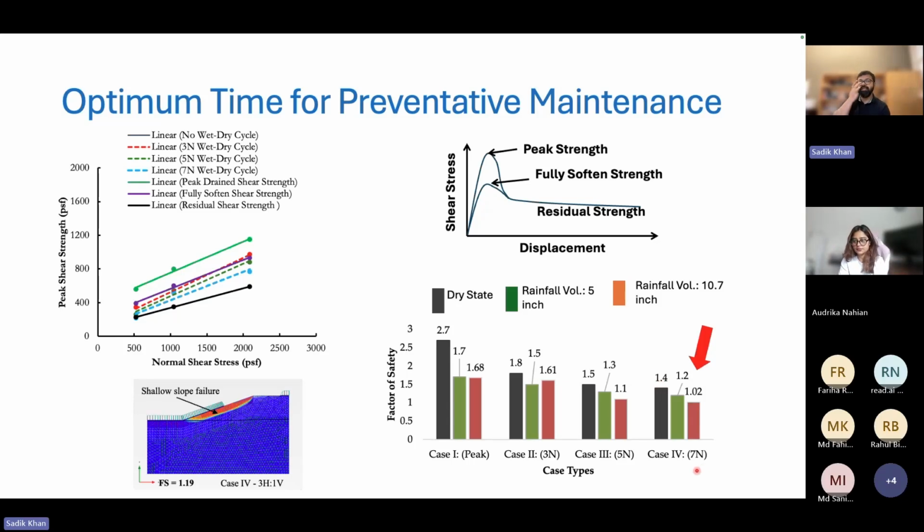particular soil. So technically, what happens there is that we can go back and find out the conditions of the slope, and how much rainfall there is. So we need to know the shear strength, the rainfall, and the permeability behavior. We can do infiltration modeling and coupled flow-deformation analysis in any software package like PLAXIS, GeoStudio, or anything else.